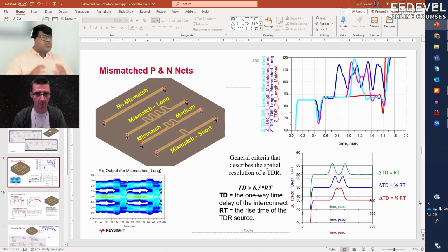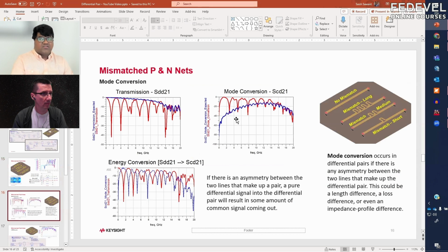It's also about where you start becoming an SI engineer; you create a bias. People who have digital design experience early in their career, or someone who comes from a PCB design environment, think more in the time domain. So the very first thing they go towards is TDR responses and an impedance profile. But someone from an RF domain will not see this. They will first plot S parameters and think in the frequency domain.